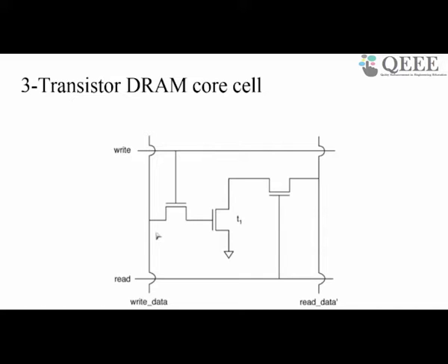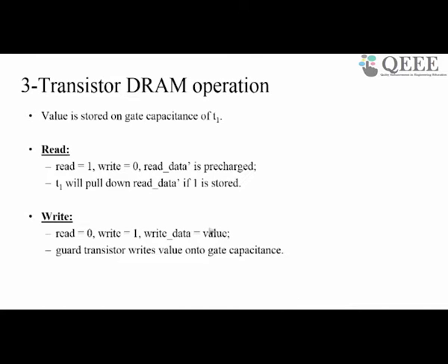In a similar manner, when you enable the write line, which will switch on this transistor, and give the appropriate data on the write data line, then if it is 1, the transistor will get charged through these lines and this charge will be retained even after you remove the assertion from the write line. So this way the value gets stored in this cell.